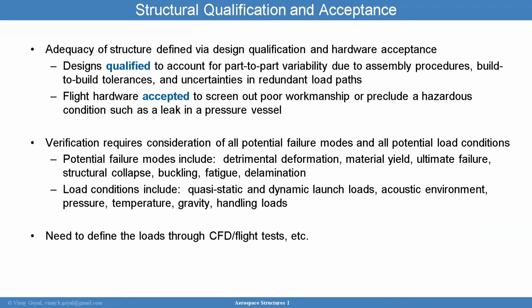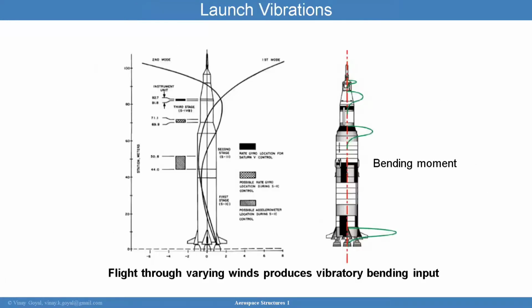The structure qualification and acceptance test of a launch vehicle heavily relies on the understanding of the aerodynamic environments. If I don't understand the aerodynamic environments, then I cannot go ahead and qualify a structure. It'll be very difficult to do. I first need to make sure I fully understand the maximum loads I will ever see. Typically, in aerospace applications, launch vehicles specifically, we're defining loads that are statistical in nature. I want to make sure it's a maximum load, but I want to make sure it's statistically defined.